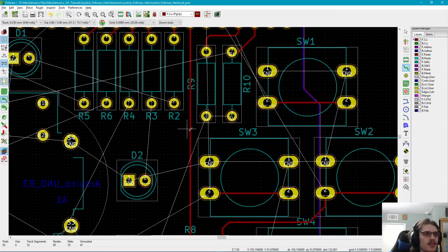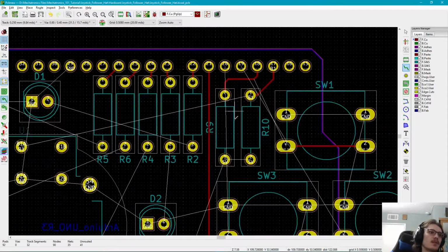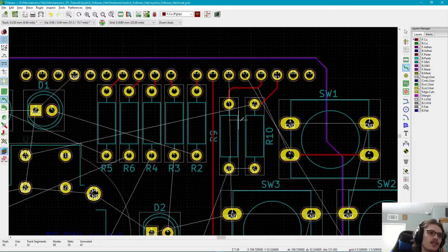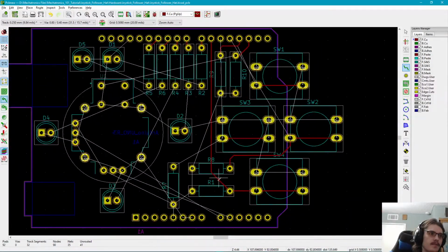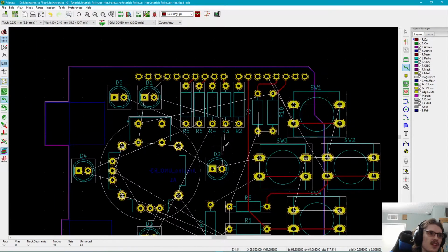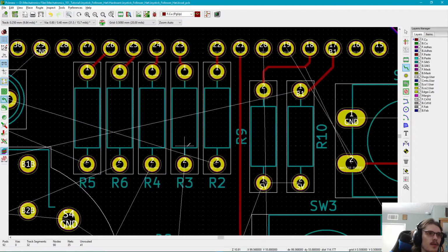If it was soldered to the board and let's say the trace blew up or got damaged, you would have to desolder the IC to check if that trace underneath is good, and that's kind of a pain. So if you do it underneath an IC, just be aware that that could be a problem.